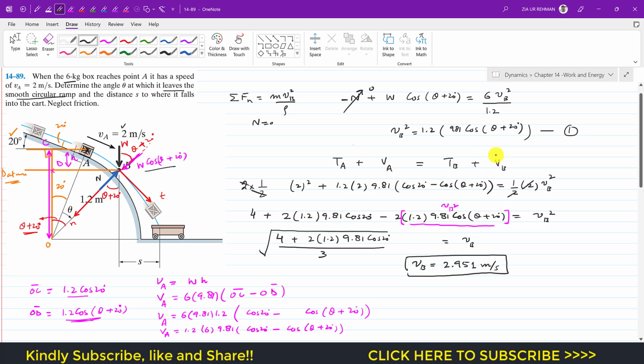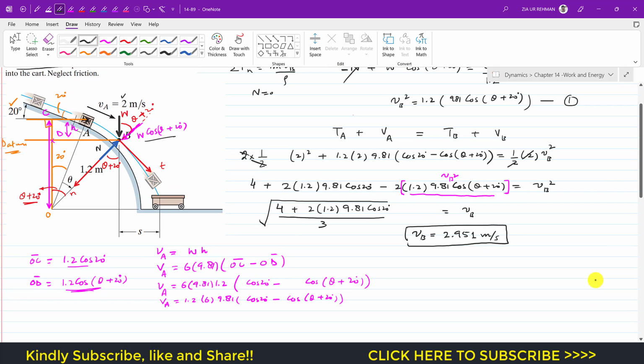So now if I put VB in equation 1, we will be able to find that theta. From equation 1 we can say that VB square, which is 2.951 square, is equal to 1.2 into 9.81 cos of theta plus 20 degrees.